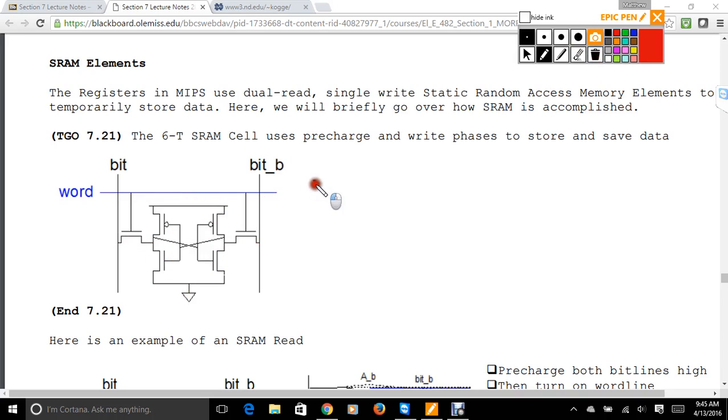Same thing, we do word line at 1, and then we put this one at 1, and this one at 0. What's going to happen is it goes through the inversion region. We have our MOS here, so it's going to go through here. It goes here. We put 0 there. We activate this PMOS. That creates this inversion region, goes through this cell, the one there, which activates this NMOS, puts a 0 through here, creates a conduction region, and we have our 0 again. And then again, we go through our loops.